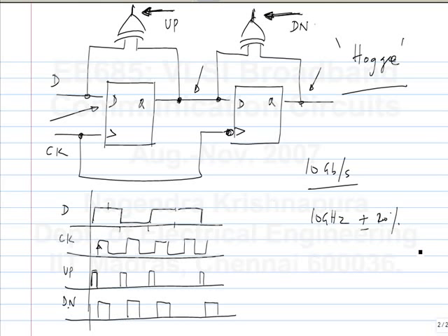So this is just the bare bones clock and data recovery circuit. A real system may have extra things. It may have something else to first behave like a frequency synthesizer. That is, it has a periodic reference input. In the transmitter there is a reference frequency. In the receiver also there is a reference frequency, but this is not exactly the same. If you make two crystal oscillators, those frequencies will always be different.